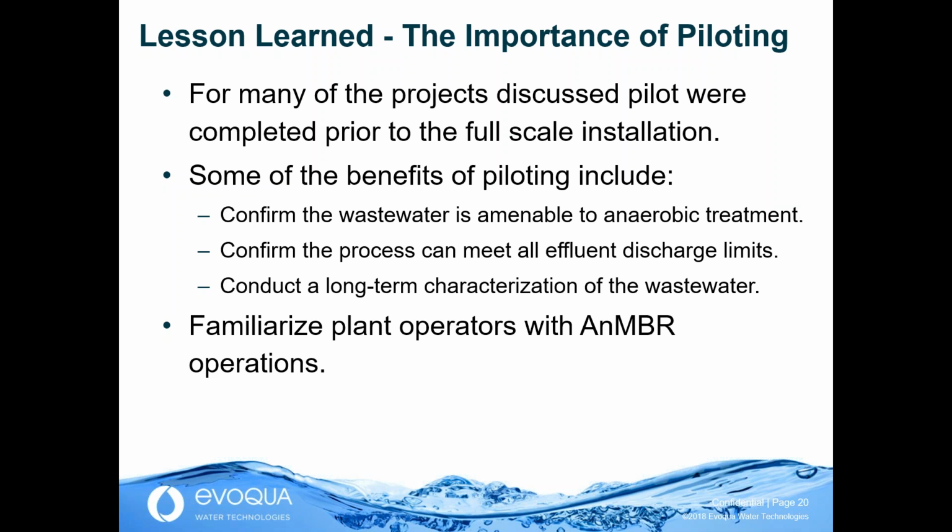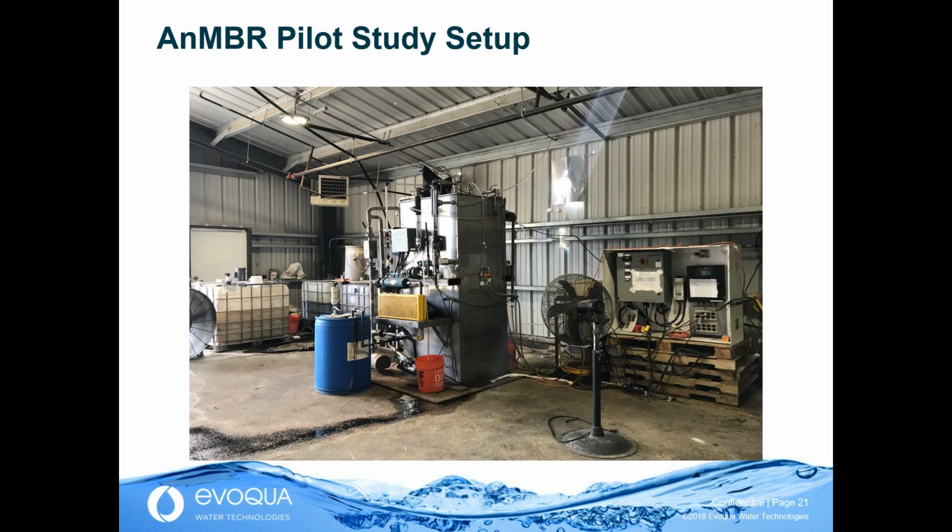It allows us to characterize the wastewater and see the impacts and changes from the raw wastewater on a small pilot system. The effluent results from the pilot can be used to size downstream polishing steps if needed. The photo here shows a pilot study that was completed last year. This pilot was operated for about 8 months, and throughout the study, many things were learned. But typically, one thing we're looking to learn during pilot studies is the fouling on the membranes or the compatibility of the raw wastewater with the anaerobic process.